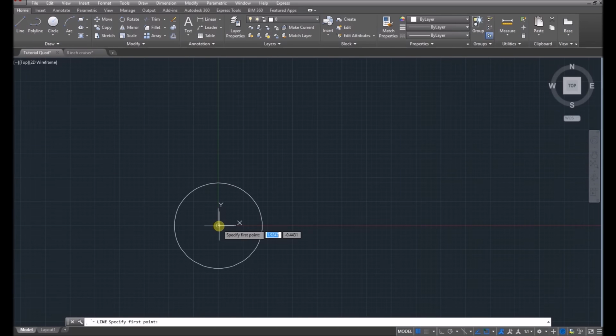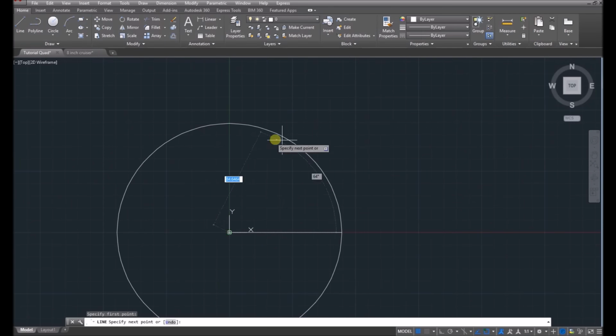Now, I am far from an expert in CAD, so I literally taught myself how to do this because I wanted to do frame designs. If I want to get to this point here, I'll just draw a line and then delete that line later. Now that I've got that line there, it lets me lock. That's probably an easier way, I don't know. Also with AutoCAD, it won't lock to the axes like, oh yes it will. See, sometimes it doesn't, and sometimes you actually have to go into the middle and draw it up from the middle. See, now it's not. There's probably some kind of consistency that I'm missing, but anyways.